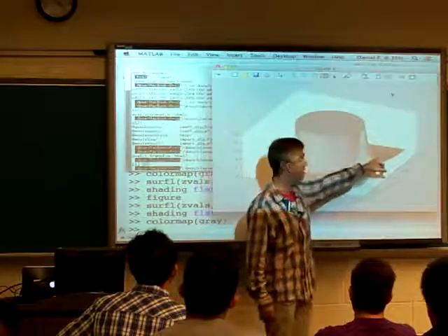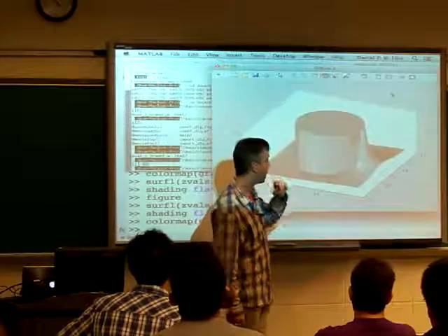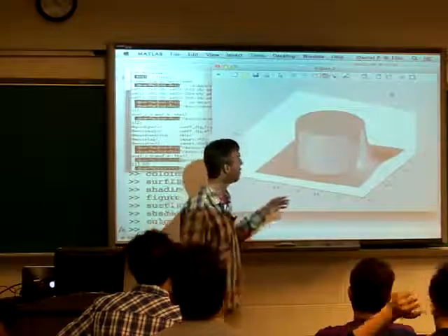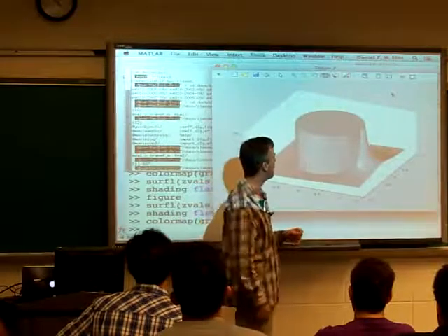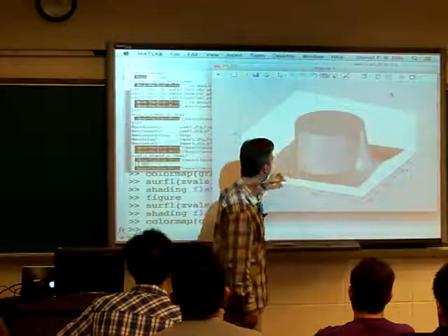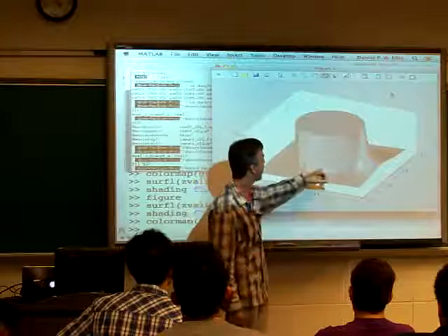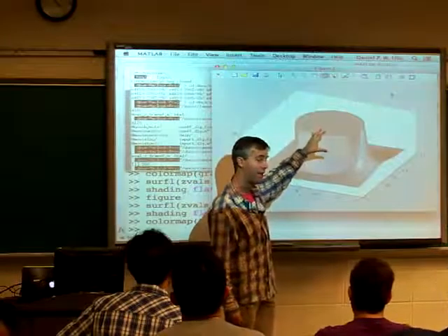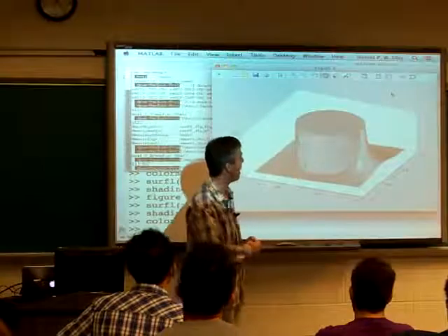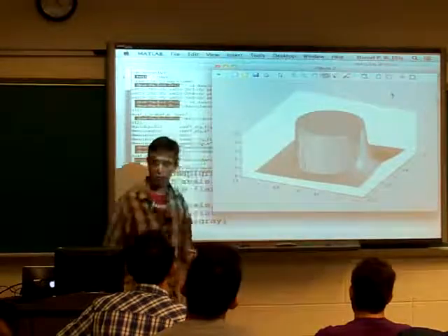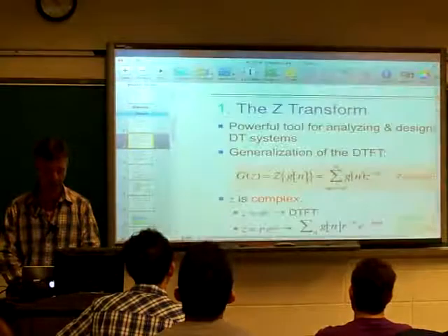And we see out here, it's nice and smooth and has this nice, interesting shape. And then there's this circular boundary where suddenly it just diverges, right? It goes out of control. And so we typically observe this with many z transforms, particularly for infinite length sequences. And so we call this range of values of z for which the value of g of z converges the region of convergence. And this range of values in here where when we try and evaluate g of z it blows up, that's not the region of convergence. That's the part that's not in the region of convergence. And we frequently get this situation where there's some circular boundary where the values do not converge.